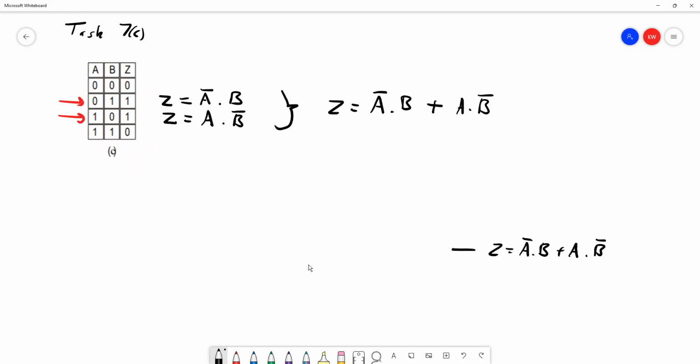As we've seen previously, because we have that plus sign, we have an OR. Either this expression or this expression will give us a 1. So these two expressions will be the inputs to an OR gate, which appears just before we get to the end of our circuit. So we have an OR gate here with two possible inputs, and these inputs come from either side of our plus sign, A bar dot B and A dot B bar.